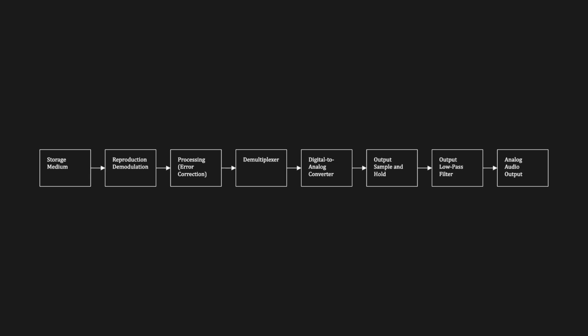To handle timing variations, playback circuits use data buffers and perform error correction. Timing and clock signals within the digital stream are identified by time-based correction circuits, which help align the signal, separate frames, and determine the value of each bit. Since most received signals have timing errors, like jitter, devices such as phase-locked loops, PLL, and buffers are used to fix them. A buffer stores data as it arrives unevenly, then releases it at a precise rate, ensuring accurate playback timing. This allows samples to be played back at the same rate they were recorded.